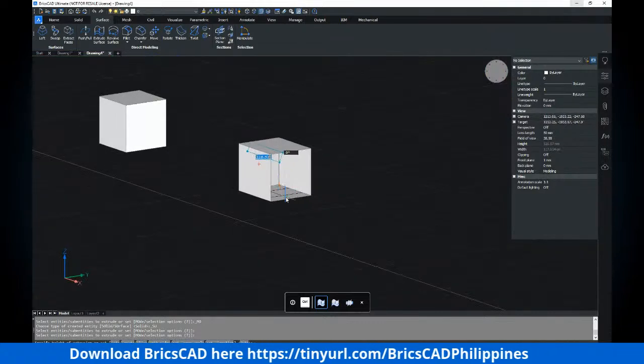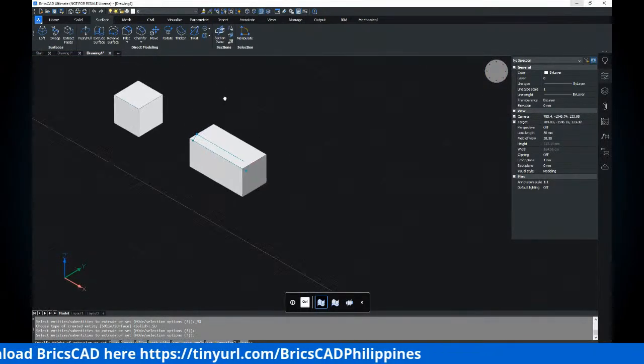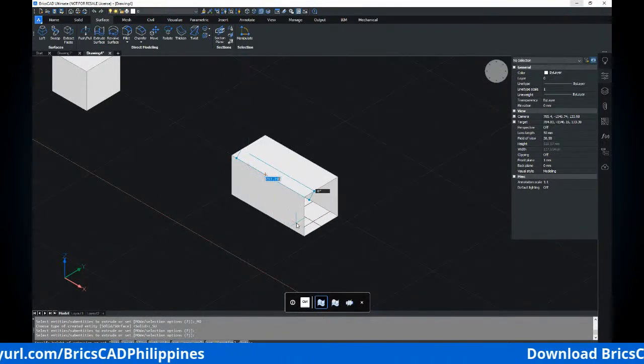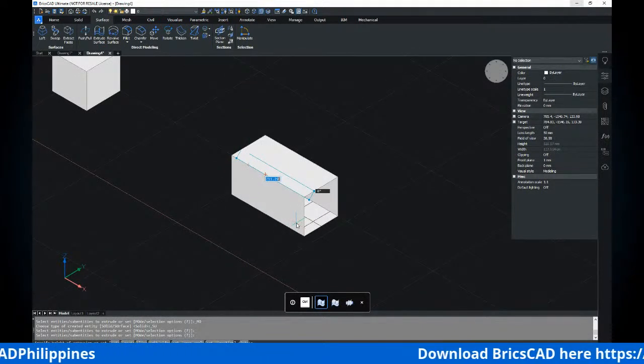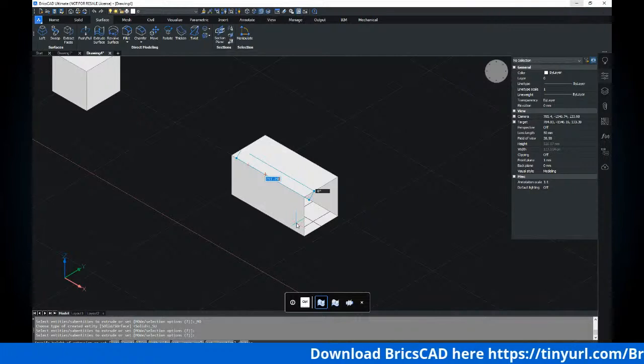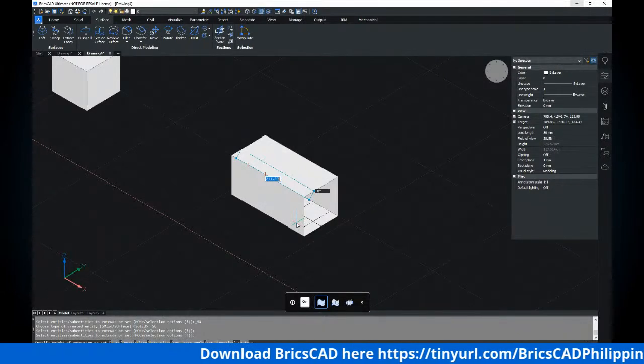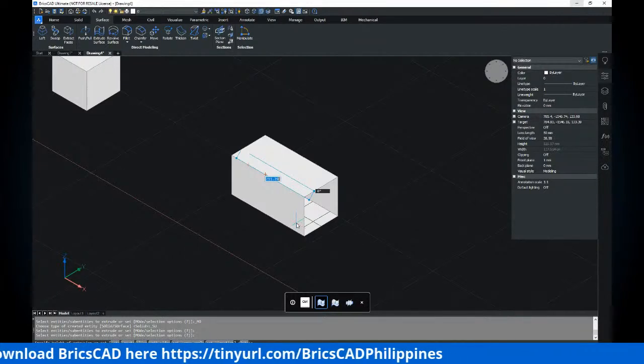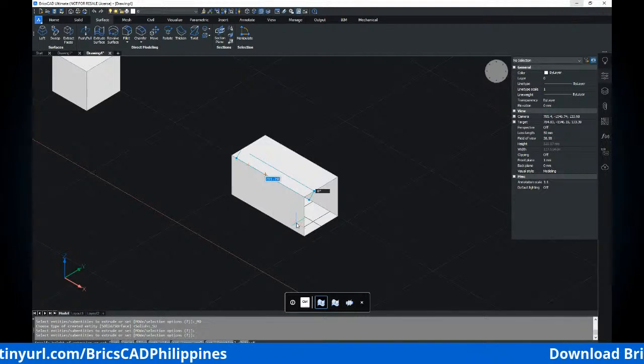So you can put a dimension, extrusion height, from this point here of the face. Then if you want to extrude the surface symmetrically, you can select both sides. So that is letter B for both sides.